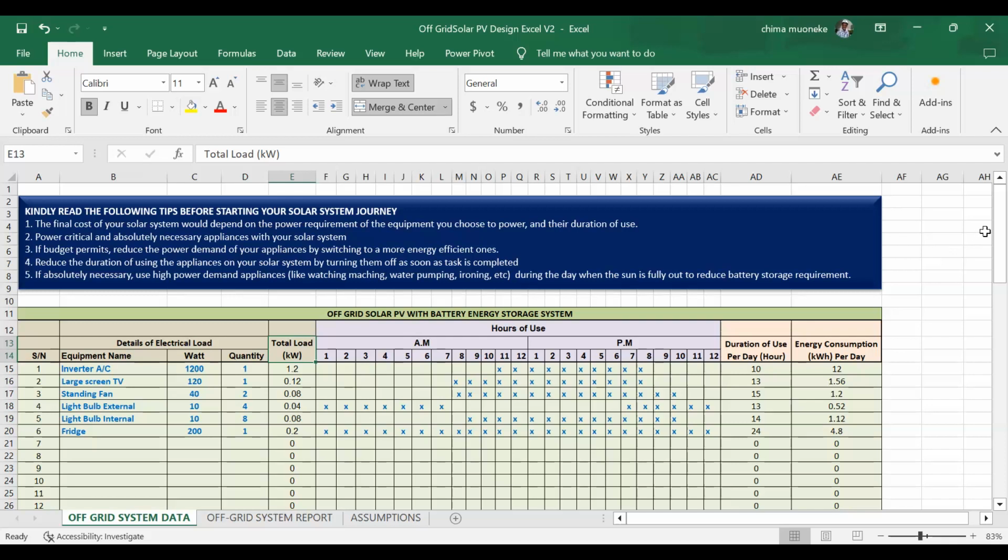But essentially, what I'm going to present to you is more like the first analysis that you can do when you're discussing with a client, because essentially you just want to know what the need of the client is. When we're talking about solar installation, you want to understand what the client wants to power. For how long does the client want to power those loads? It must not be accurate, but a good estimate will be very helpful in running your design and sizing.